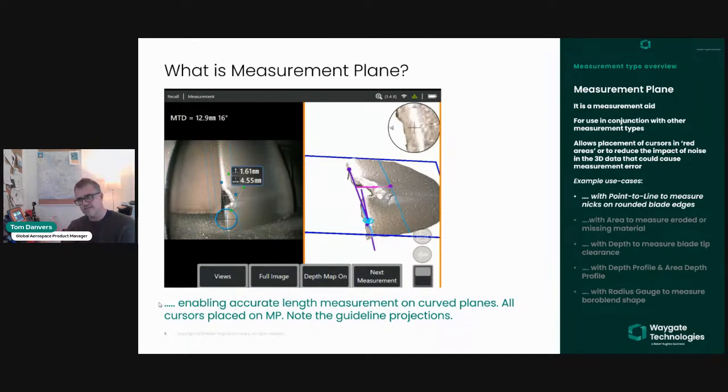So you can see the distance has changed from whatever it was, but I can't remember what it was, to 1.61. And what you've heard me say many times before in previous sessions, always check your point cloud to make sure that not only is it, obviously, conforming to the measurement plane, but you have the ability to adjust your cursors and make sure that those cursors are correct.